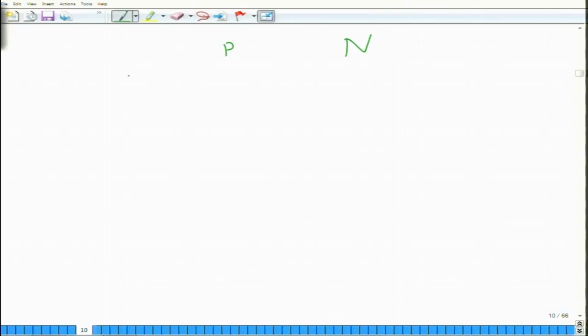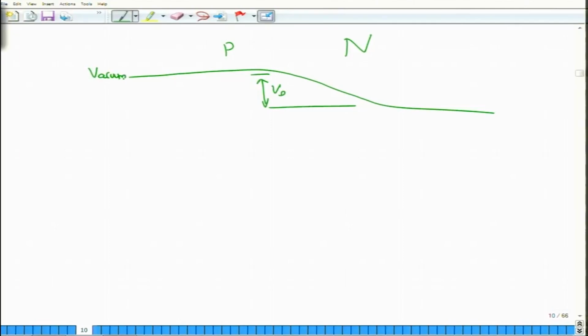The difference here now is that the vacuum level actually starts to bend. The amount of bend that the vacuum level undergoes, well, it is not really a sharp bend, it is a gradual transition, but nevertheless this small amount of bend is the one that actually sets up the corresponding built-in potential, or the junction potential, between this small p and capital N junction material. So, the vacuum level actually undergoes change, but it is a continuous change. So, the levels continuously change from the small p region to the capital P region.